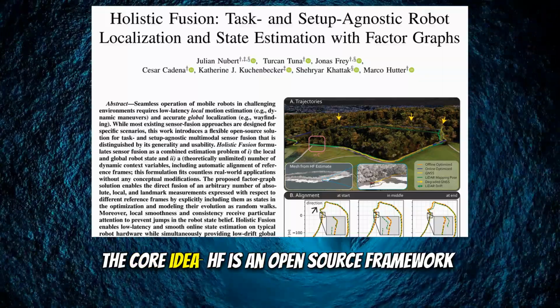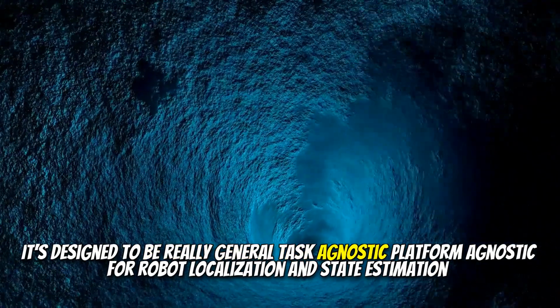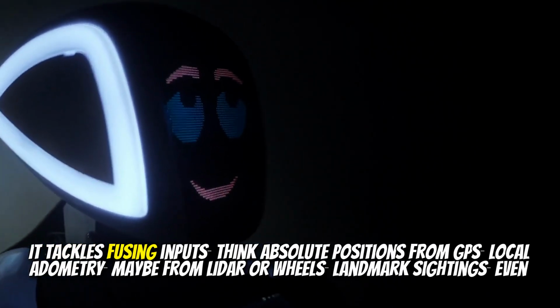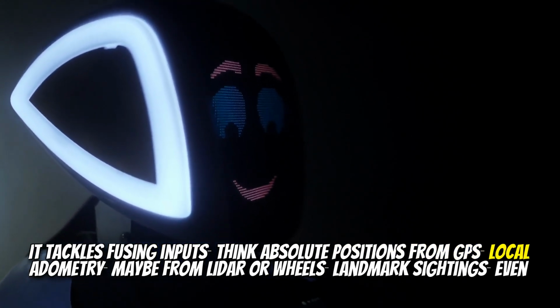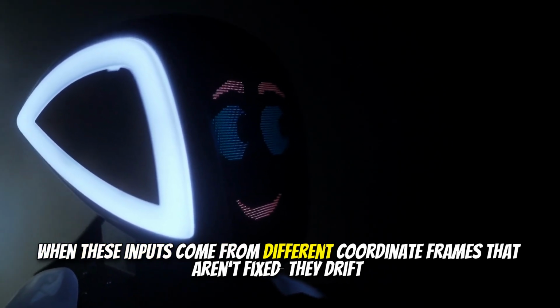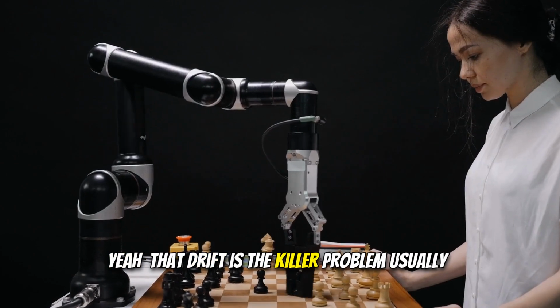Right. The core idea. HF is an open source framework. It's designed to be really general, task agnostic, platform agnostic for robot localization and state estimation. And its big innovation, it tackles fusing inputs, think absolute positions from GPS, local odometry, maybe from LiDAR or wheels, landmark sightings, even when these inputs come from different coordinate frames that aren't fixed. They drift. Yeah, that drift is the killer problem usually.